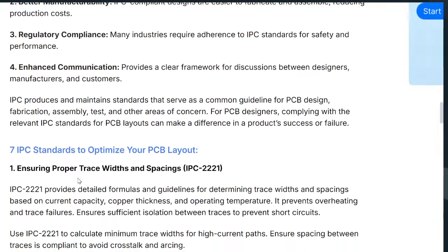All these three parameters, see, even for inductors, in the RLC parameters, L is dominating, inductance is dominating, but it still has R and C inside internally. Even a coil, for which we usually use the inductor symbol when placing it in schematics, does not necessarily mean that it has no resistance and capacitance. RLC parameters are always present.